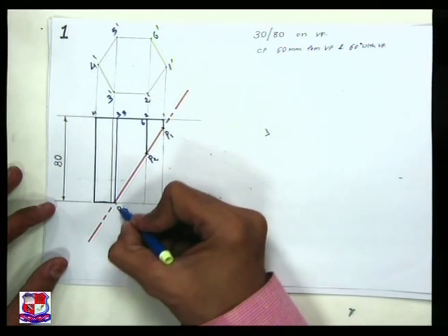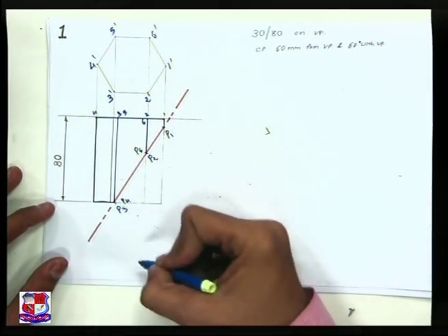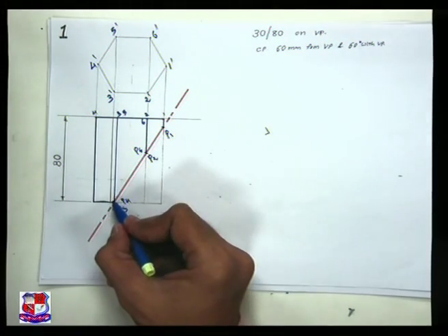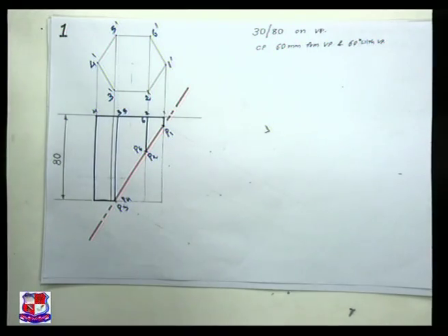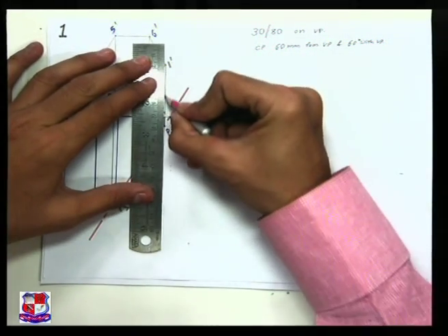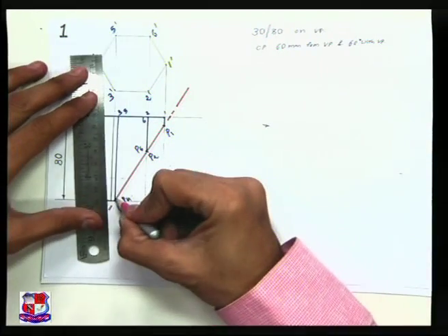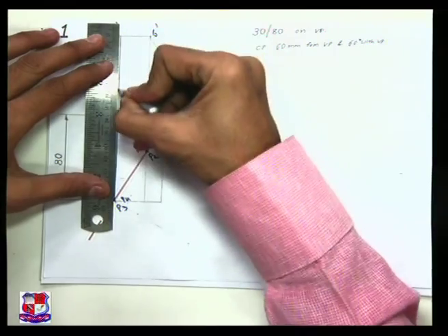Here 2 points would be there, P3 and P4, and here the P6 point would be there. Right, 2 points are here, 2 here, 1 here. Now I didn't locate the position of these points in the front view. So for that, from here draw a straight vertical line, from here a straight vertical line, and from here a straight vertical line, like this. That is the projection line.